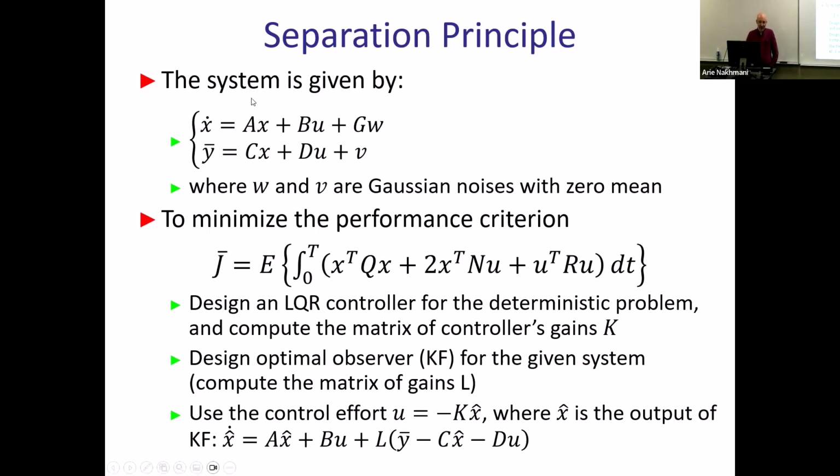So given your system in that kind of form, which is Ax plus Bu plus Gw, where Gw is the part of uncertainty of your system or disturbance, and given Cx plus Du, you don't have to use D, but since I'm not proving anything anymore, I can give you full formulas for the entire thing with D. The same formulas work for a regular observer and regular controller. I just typically ignore D because I needed to do computations and calculations, so I assume D equals zero, but you don't have to.